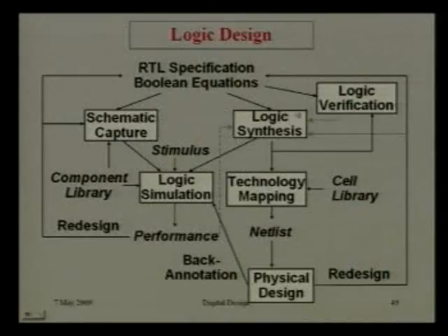Then it is technology mapping, meaning, as I just told, for digital circuit design, this is the cell library. So this is called technology mapping. That means the actual technology is coming in there. What is used in the fab lab is given as a library in your lab, that you are taking when you are synthesizing. So this is actually technology mapping.